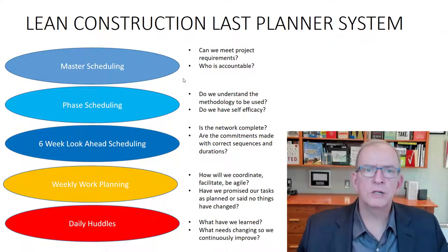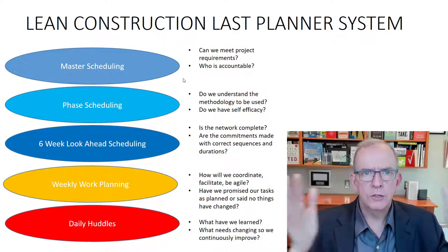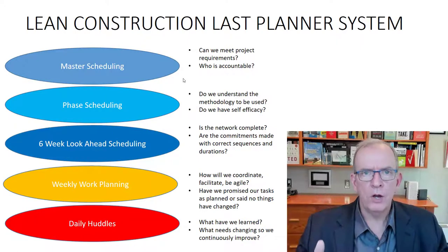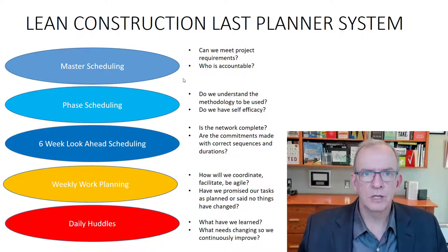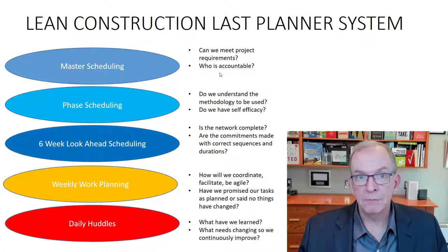But Last Planner system can be brought into any kind of contract, just that when you bring it in may be affected by the contract type. So lump sum, you'd be using it from when you first start pre-construction planning. So we have this master schedule development, and we try to institute as many procurements as early in the process so we can get inputs.